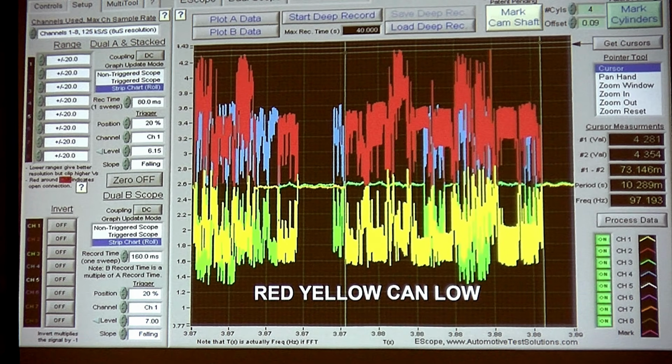You know that because if you're looking at an O2 sensor and you've got the frequency at the fastest part of the waveform, all you see is this line popping up and down. There's no definition. I've got to slow the scope frequency down to be within a certain margin of the signal I'm looking at so I can trace that waveform out and it's a meaningful waveform. If I'm faster than the signal or slower than the signal, there's no meaning to the signal. I alias. I don't have the data that I need to make decisions off of, right? The frequency of the scope has to match the signal.